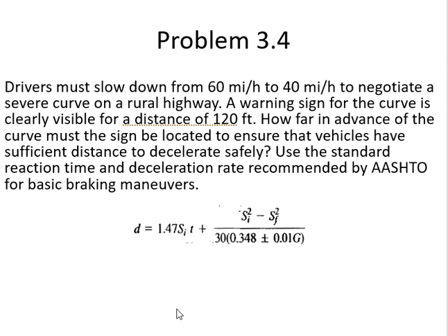So I have this equation. I have to go from 60 initial, 40 final. Rest of the values you can take as standard. Reaction time 2.5 seconds, and this remains as it is. So give me the distance here. How much distance he needs to stop? Oh, sorry, to slow down.